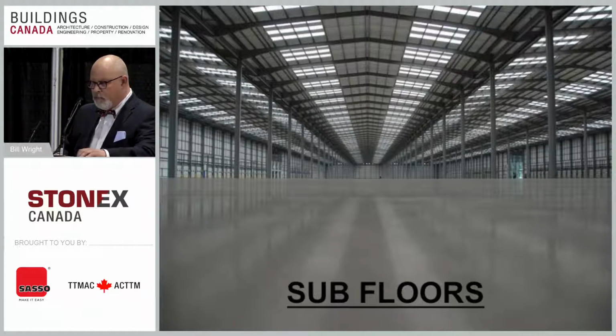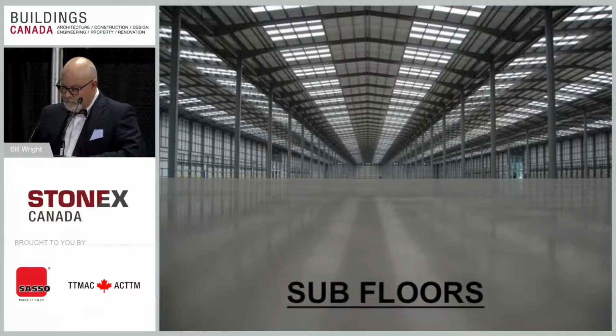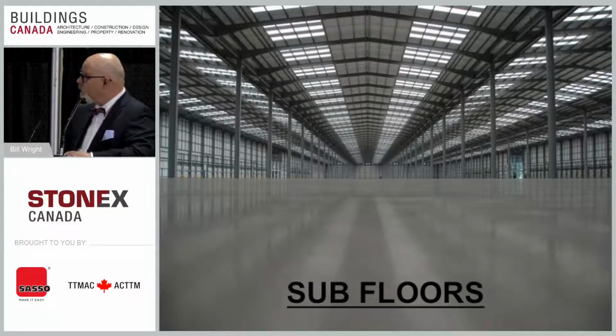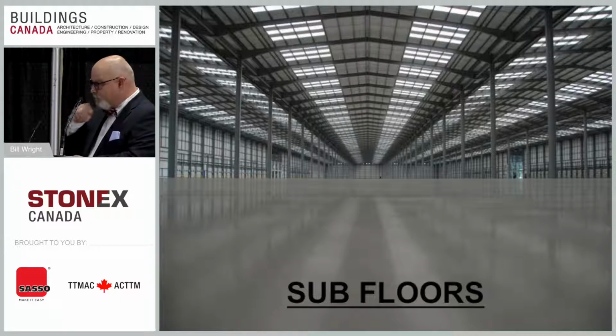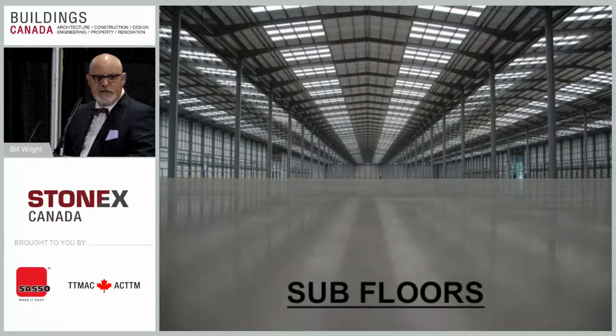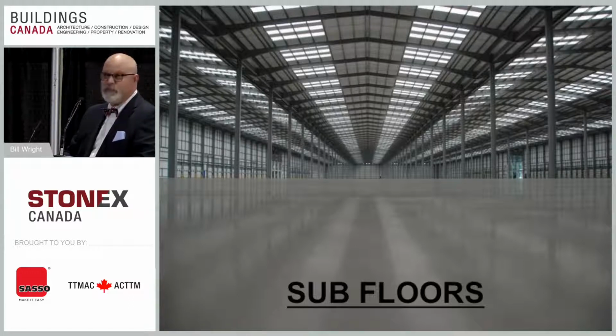Subfloors, we talked a fair bit about that already in terms of the floor flatness. Generally, we're using either hollow core, pre-stressed or post-tension types of concrete assemblies. Again, all the same things apply in terms of the flatness. I told you the best cement guys in the city can get to about 6 millimeters in 3,000 millimeters, and we need 3. So again, back to preparation, we want good flat substrates.